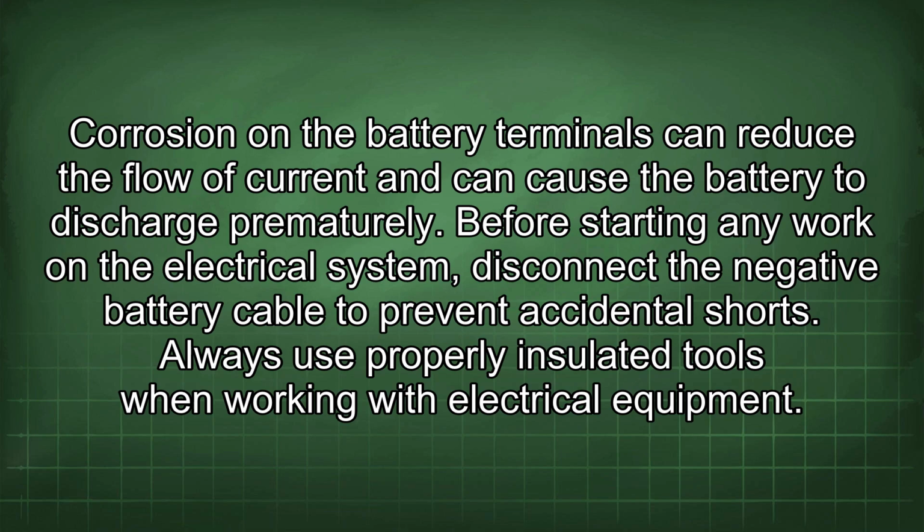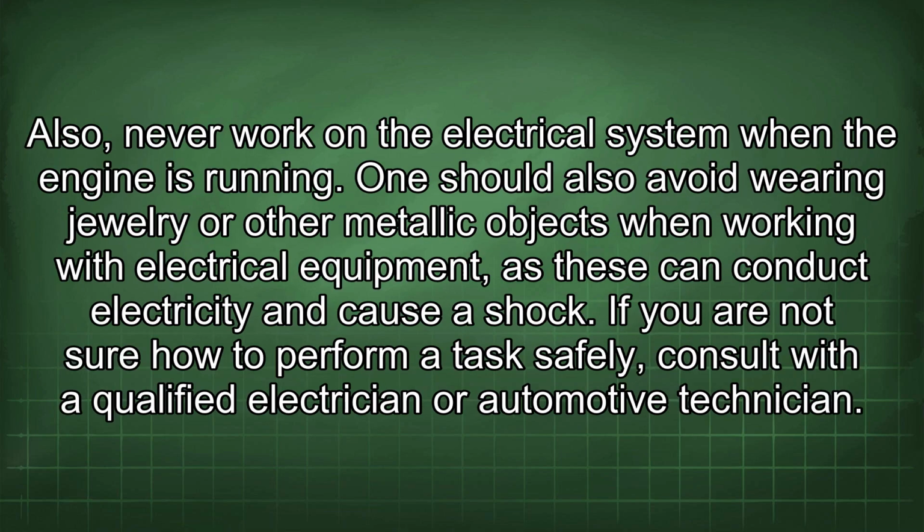Before starting any work on the electrical system, disconnect the negative battery cable to prevent accidental shorts. Always use properly insulated tools when working with electrical equipment. Also, never work on the electrical system when the engine is running. One should also avoid wearing jewelry or other metallic objects when working with electrical equipment, as these can conduct electricity and cause a shock.